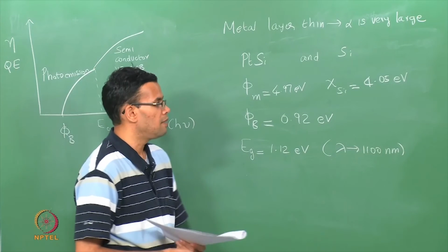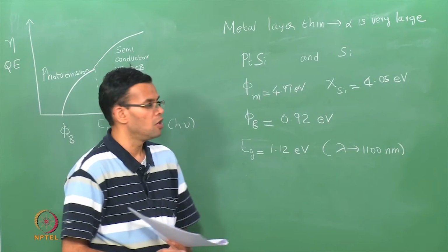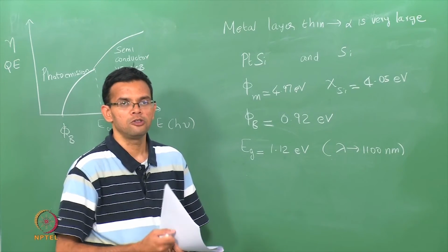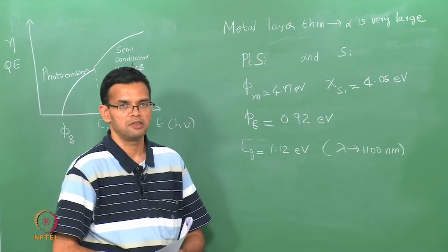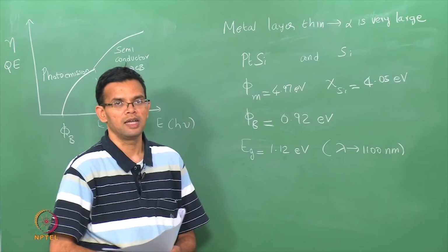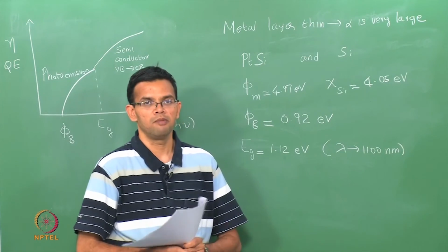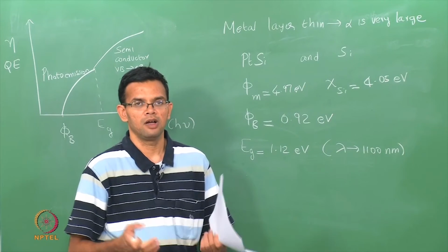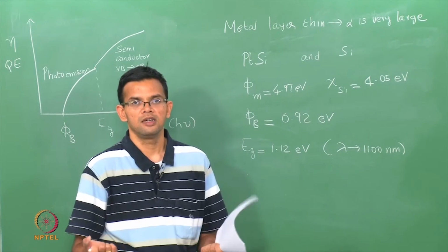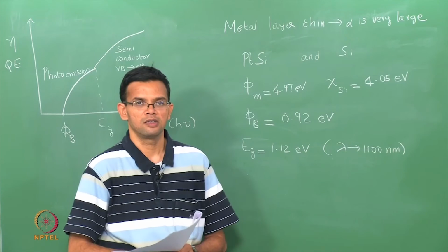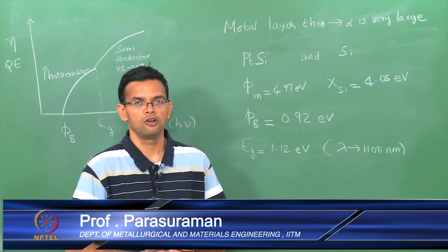So, we have looked at 3 examples of photodiodes. So, you have a simple p-n junction or a pin or a metal semiconductor. You could also have a phototransistor. In this case, you have a regular bipolar junction transistor, which we have seen before. It has an emitter, base and a collector. So, in this particular case, you modify your simple bipolar junction transistor to have a larger base, so that electron hole pairs are generated within that, and this in turn gets separated and forms your current. You could also have a heterojunction based device from your transistor in order to improve the gain.